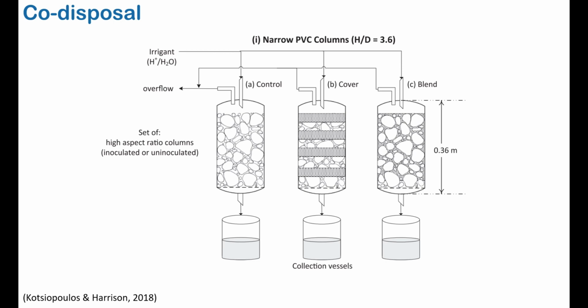The study used two packing protocols: a layered configuration where alternate layers of benign tailings and coal interburden were packed in the column, and a blended configuration where the benign tailings and the coal interburden were mixed together in the column. The blended approach was used to assess the effectiveness of using benign tailings to blind the sulfide-rich interburdens to oxidants, and the layered approach was conducted to develop capillary barriers with cascading neutralization. They found that ARD prevention was largely dependent on the restriction of flow through the bed.